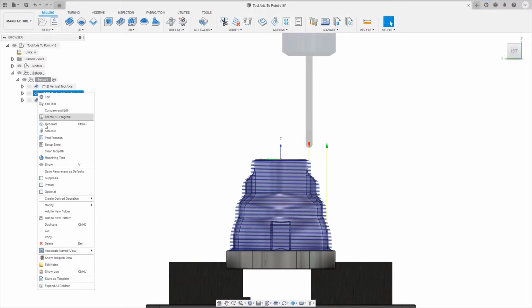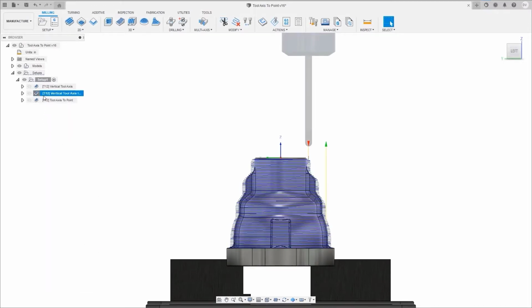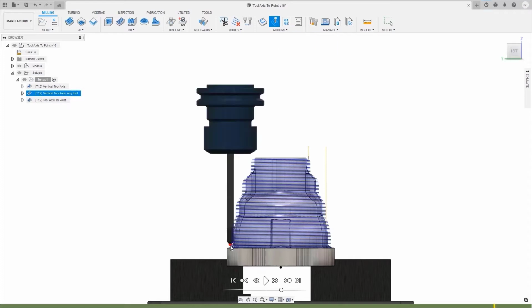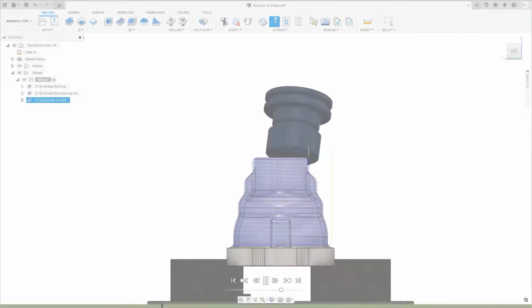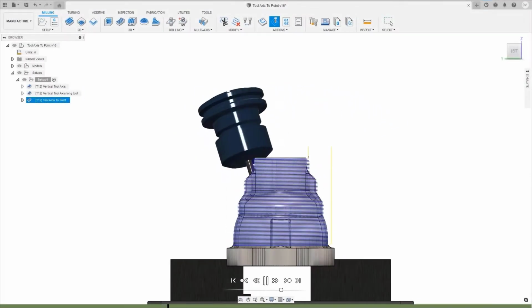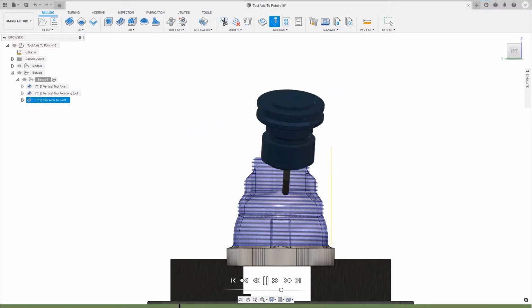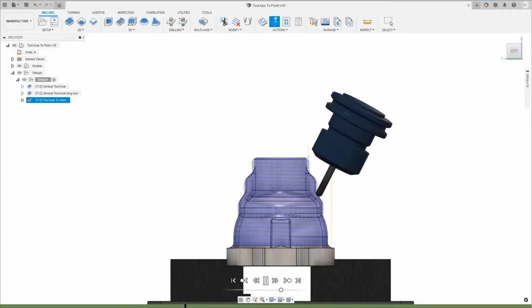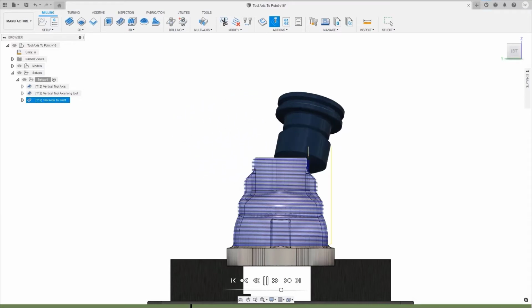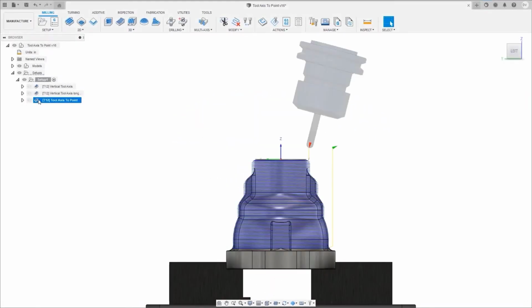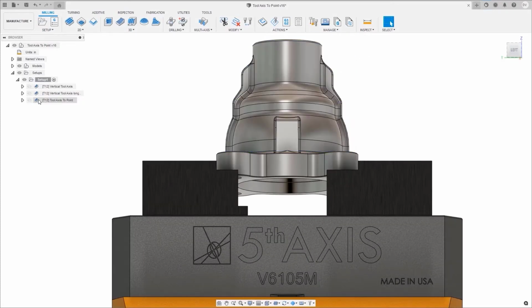While we could choose to lengthen the distance of the tool tip to the holder for clearance, the cutting conditions would become less than optimum as vibration of the tool would directly affect surface finish and tool wear in an undesirable way. We could resolve issues like this, as well as create better cutting conditions, by defining a different tool axis, which allows clearance for the tool holder while keeping the shorter, more rigid tool length during the machining process. Let's now look at the third toolpath and review the tool axis settings.